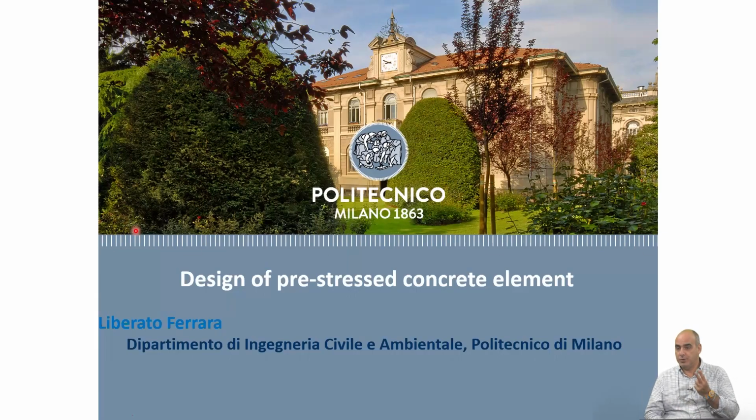But when concrete cracks, there are two issues: that you lose a part of your cross section, so your stiffness decreases. Your element becomes much more deformable. And this, as we saw yesterday, is a problem of serviceability. Your structural element may be no longer fit for use.